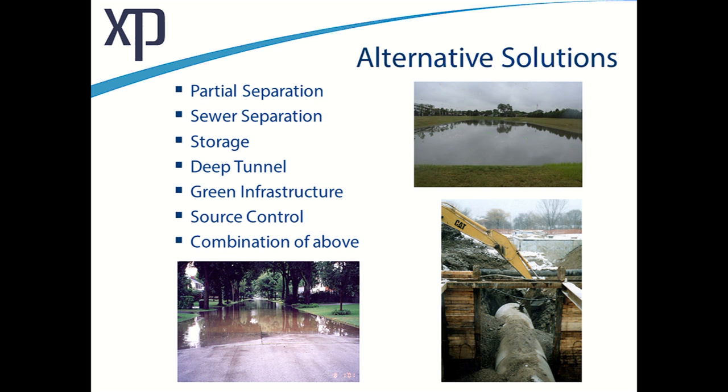A minute now on alternative solutions. We have partial or complete sewer separation. Personally, I am a little concerned about that because I think in the next years we will see stormwater treatment, and I'm worried that if we were to recommend separation, we end up telling our client, well, yeah, but now you have to do stormwater treatment in the future. So just something to keep in the back of your mind as you're looking at it.